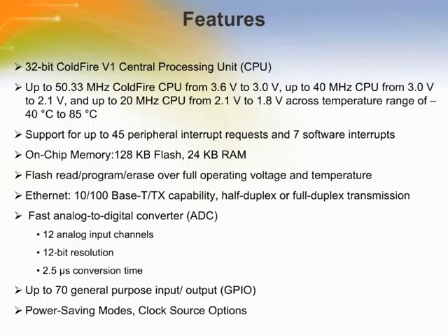Backed by Freescale's extensive development ecosystem, the highly integrated MCF51CN devices combine a 10/100 base T fast Ethernet controller, FEC, and Media Independent Interface, MII, to give developers an easy way to connect an external physical layer, PHY, transceiver. This device also includes a multifunction external bus and multiple communication interfaces for various Ethernet gateway applications.